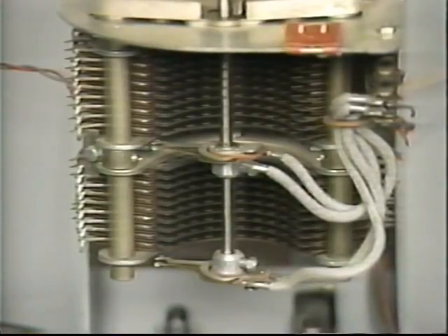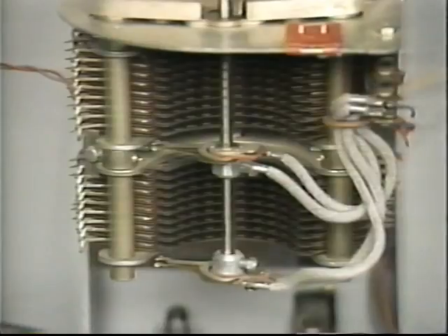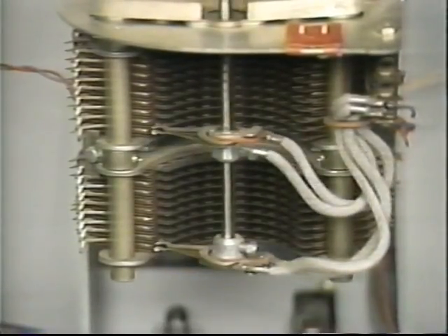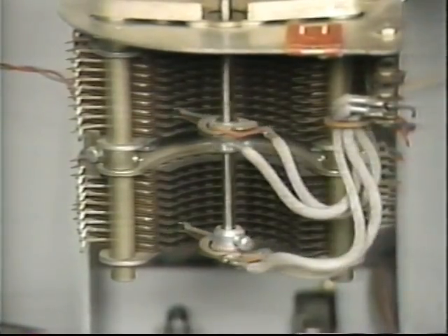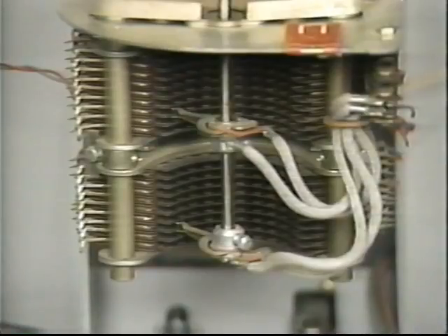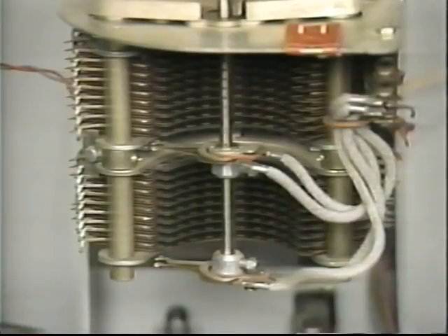Now, if your telephone was connected to this stepping switch and you were going to call one of the other subscribers, as an example, say subscriber number 32, if you had a 2-digit telephone number, the first thing that would happen would be you would dial the 3 and the armature would step up 3 times. Then you would dial the 2 and the wiper would move 2 positions over. So 3 up and 2 over is position number 32, and subscriber number 32's telephone would ring. After the call was completed, the switch would restore to allow another call to be placed.